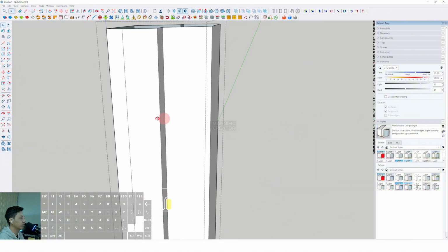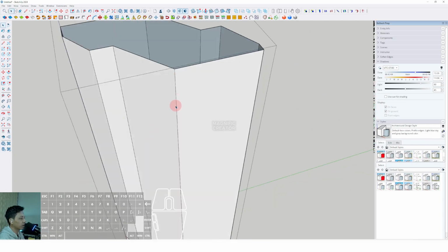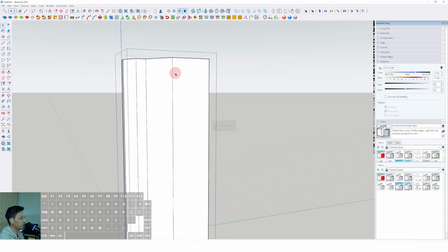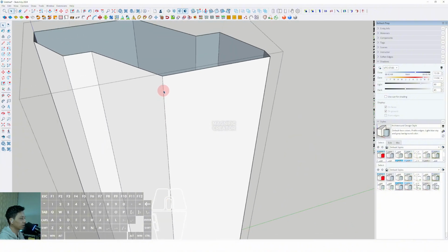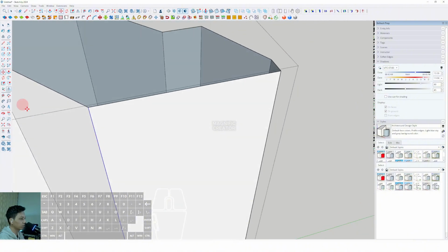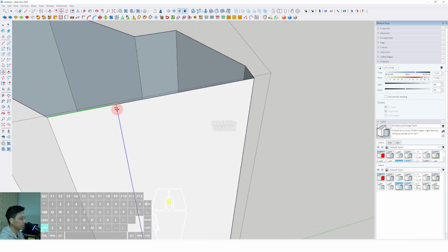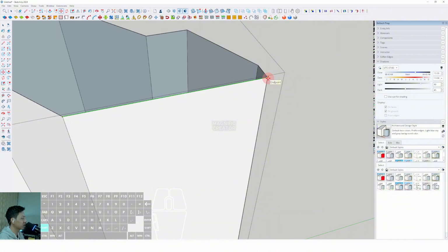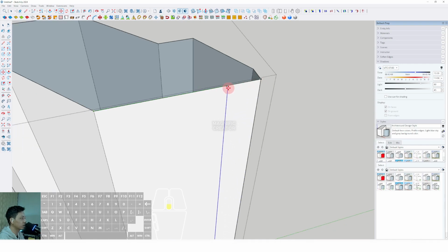Okay, now we can continue to duplicate the vertical line to make the presentation of the frame of the curtain wall. Then we can click this vertical line and we can select move, tap control, click from this point until this point. Then we can see about the distance. It's 49 meter approximately, so we can type 47 or 46. So we just decrease the 2 point from the distance. Okay, for example, we can direct to this point and then we can type 47 and slash and enter.